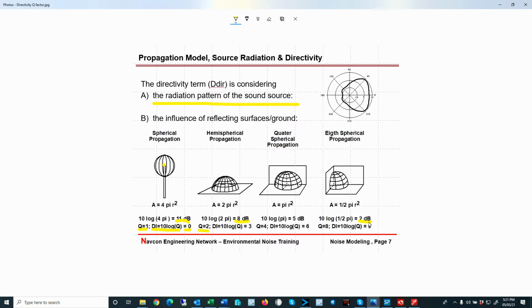By having two sources, the direct and the reflected, you would get an increase of 3 decibels. Or you could assign to the source that is on the wall a K omega correction. That correction is typically automatically set by K omega of 3 decibels or 6 decibels, depending if you have a single vertical wall or a two-dimensional corner like on the very right, where you have basically two walls radiating into an eighth sphere.